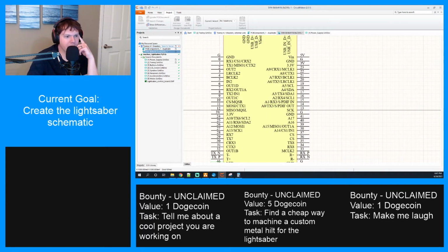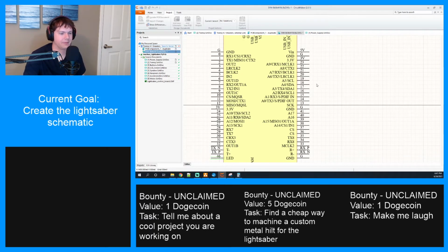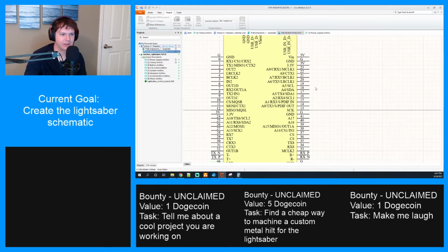It's throwing an error because some of these have the same name, because these are both ground pins, for example, and they're both named G, which should be allowed because they're internally connected, so that would make sense, right? So I'm trying to figure out a way to either turn off that error or make it allowed, because I don't want to rename them like G0, G1, G2. But it's looking like it's going to try and force me to do that. But somehow before they've done this, so I don't know if the rules have changed in a later update or what.